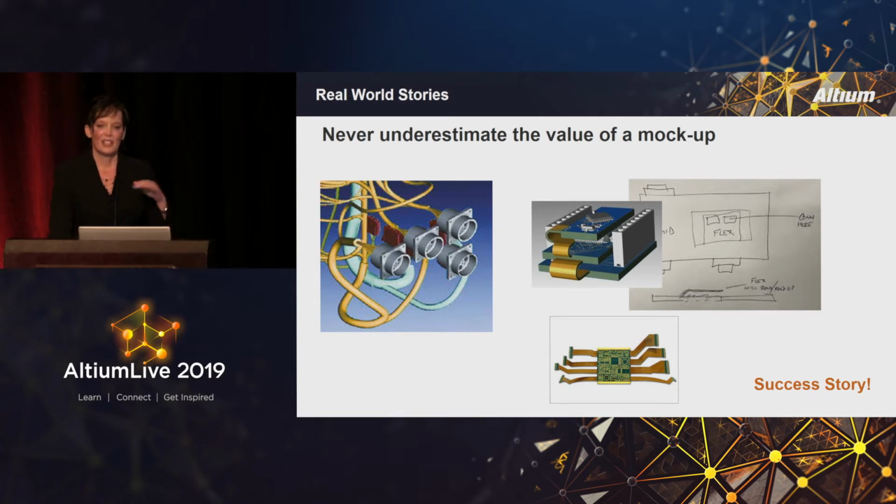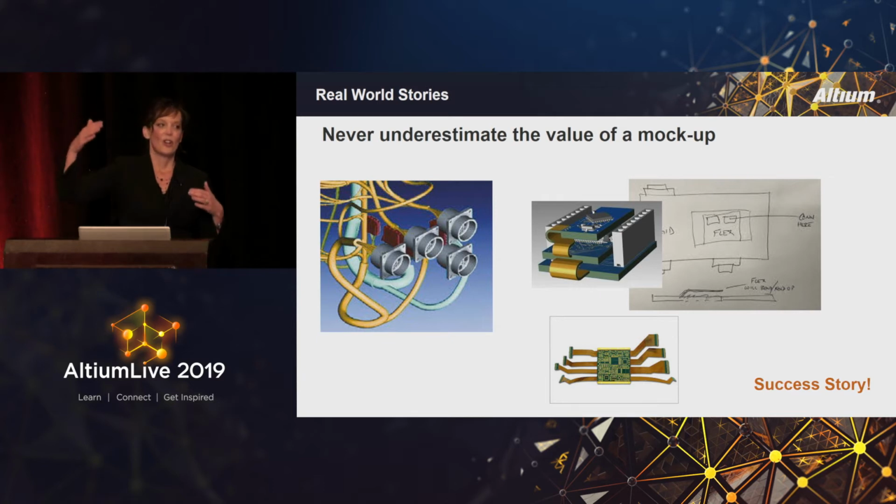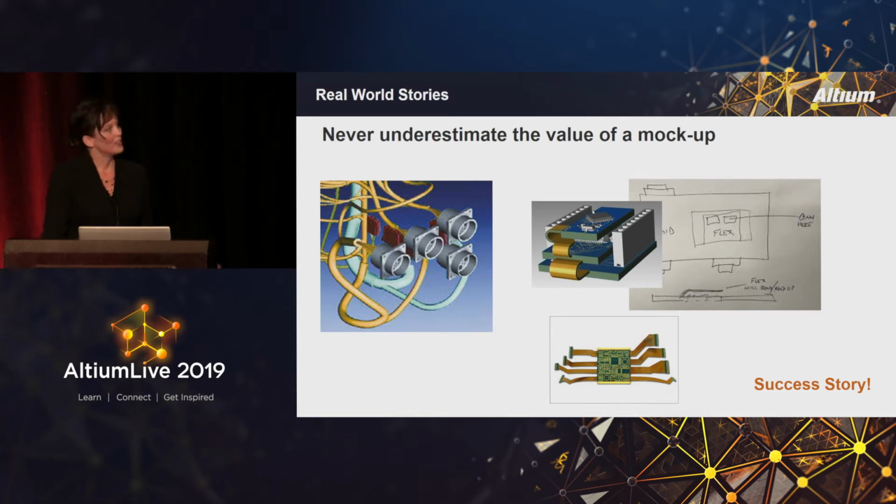I think they had dummy rigid boards, but the flex they actually etched exactly as it was going to be run, and then installed that, uninstalled it, and were able to really look and evaluate how that flex was connecting, making sure that was right, and on top of that, making sure they weren't going to have trouble with cracking or broken traces. So I thought planning that ahead of time and working with your fabricator really solved a lot of problems for them.